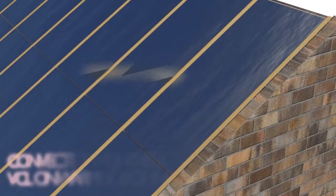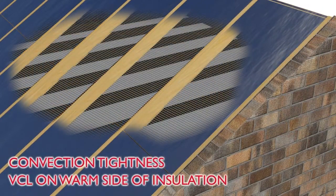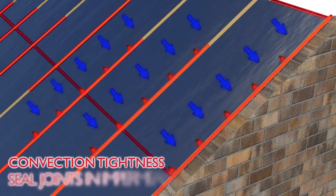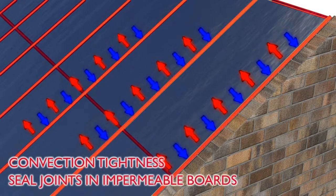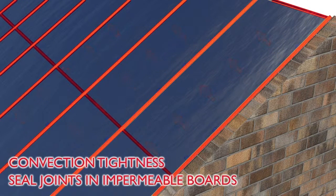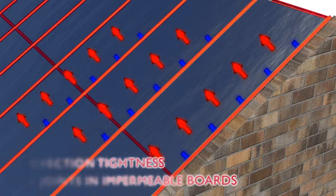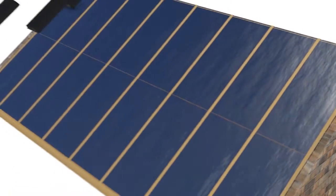In roofs of this kind, ensuring convection tightness is important, and this can typically be achieved either through the use of a dedicated vapour control layer on the warm side of the insulation, or by using insulation that's itself convection tight, such as sealed foil-faced rigid foam. This convection tightness ensures moisture-laden air cannot bypass the insulation into colder areas of the roof.